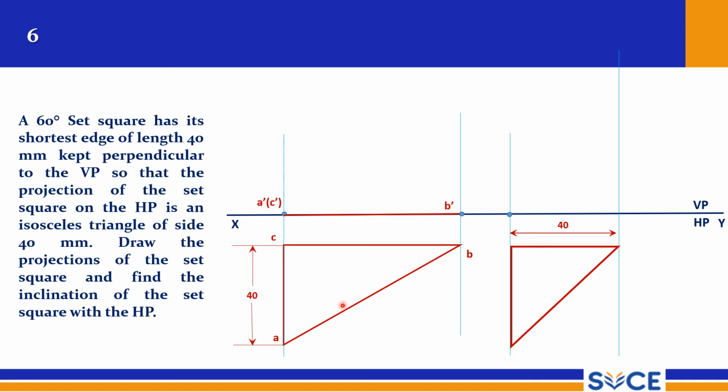And these are the points A and C, right? A1, B1, C1, and the corresponding front view points are A dash and C dash. Now students, measure this distance. Now with this point as center, on this projector you cut the arc. To cut this arc, don't forget to take this distance, measure this distance, and from this point cut an arc on this projector. And now you just mark B dash, and this is the front view now, right? So now we are going in an indirect fashion to get the theta.